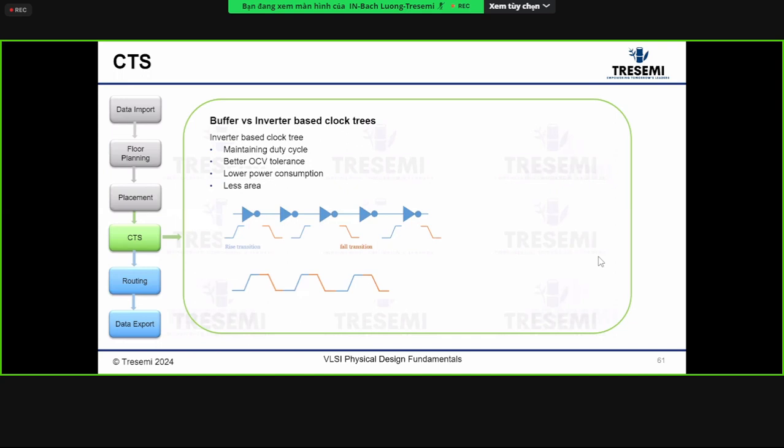But you need to understand the impact of the rise and fall of the edges, and be careful not to invert the clock edge, especially when you are driving a positive edge flip flop. If the last stage is missing an inverter and the edge is falling, then you just skip half a cycle and that flop may not latch the data you need.